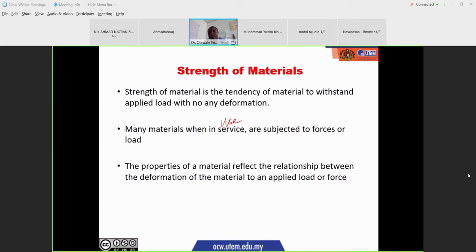So very quickly, I'll be looking at the difference between elastic deformation and plastic deformation. When you apply a load on your material, there are two things you experience. One, you can experience elastic deformation, and two, you can experience plastic deformation. Now, I'm going to illustrate with a few things here. Now, a ruler, if I apply a load at this point, there is deformation, is that right?